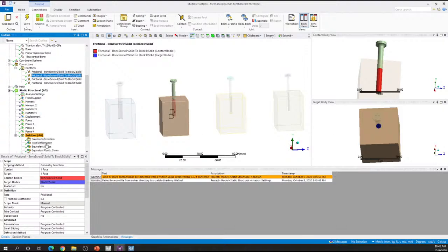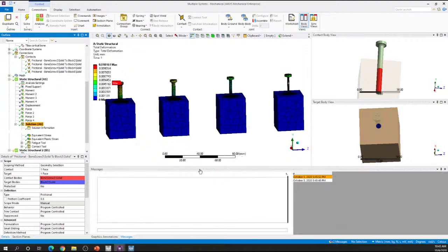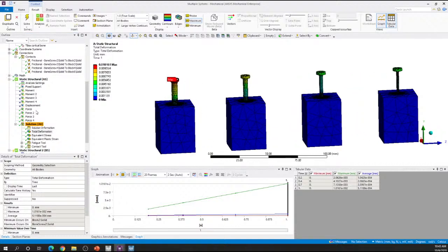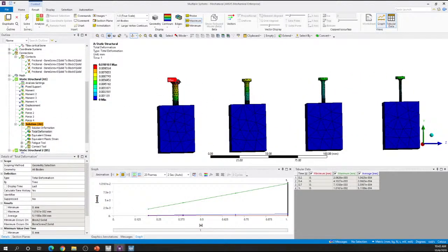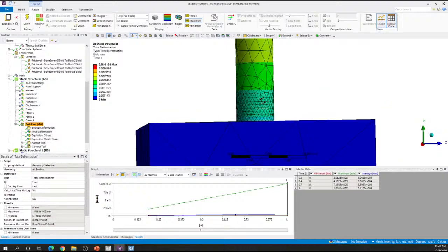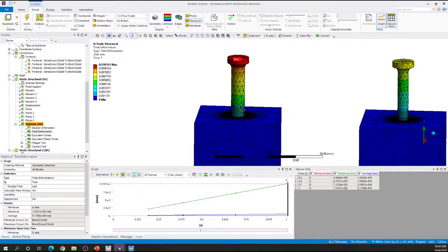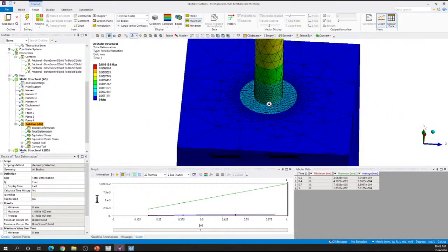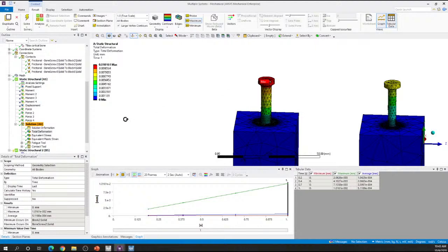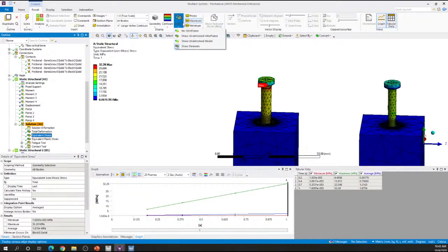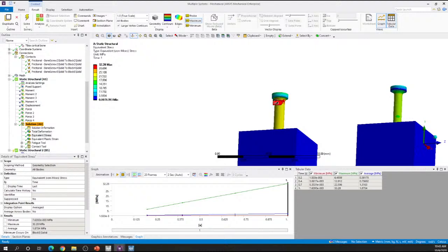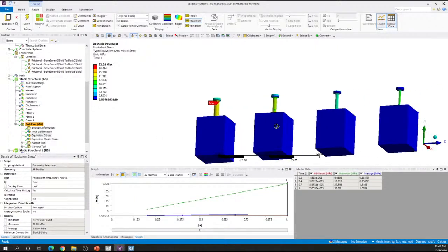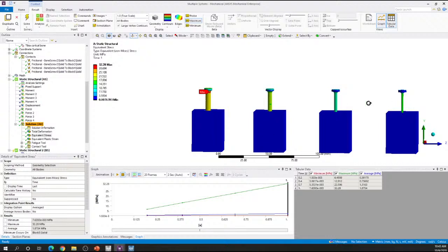And what this allows us to do then is look at the total deformation. So I apply the force, and you can see the largest screw actually deformed the most. I refined the mesh in the threaded region to try to increase the accuracy. You can see the threaded region is carefully modeled. This moves the most. The stress is the highest. Let's get rid of the wireframes. Here on the neck of my thickest screw. So if I was to apply for approval, I would say, well, based on these simulations, my large thickest screw is the one that's most likely to fail. So I would need to do testing on that, but the rest are much less in terms of the stress.